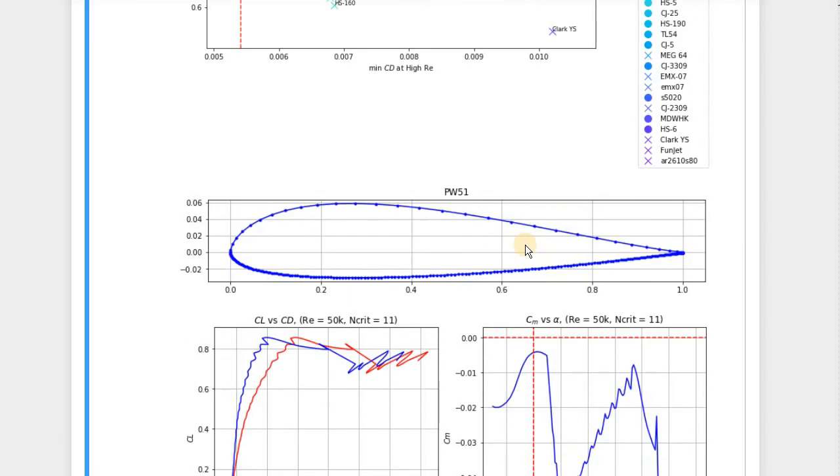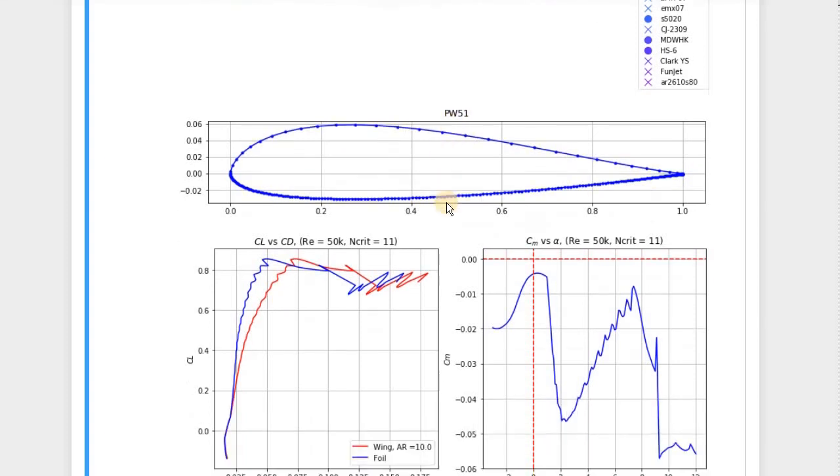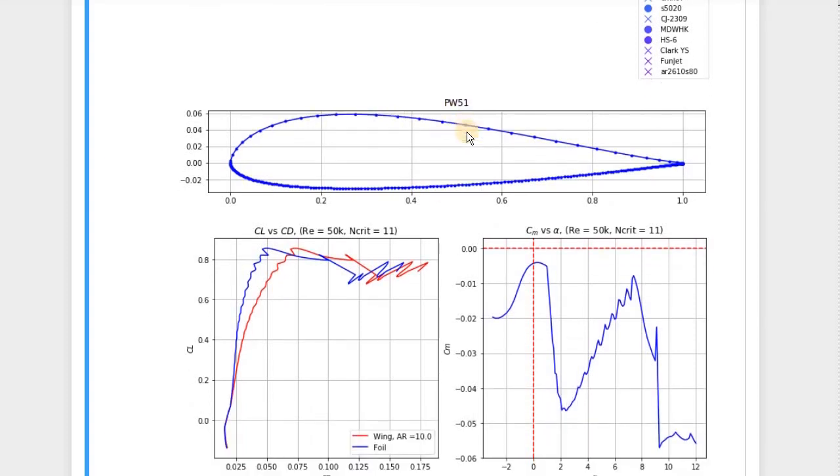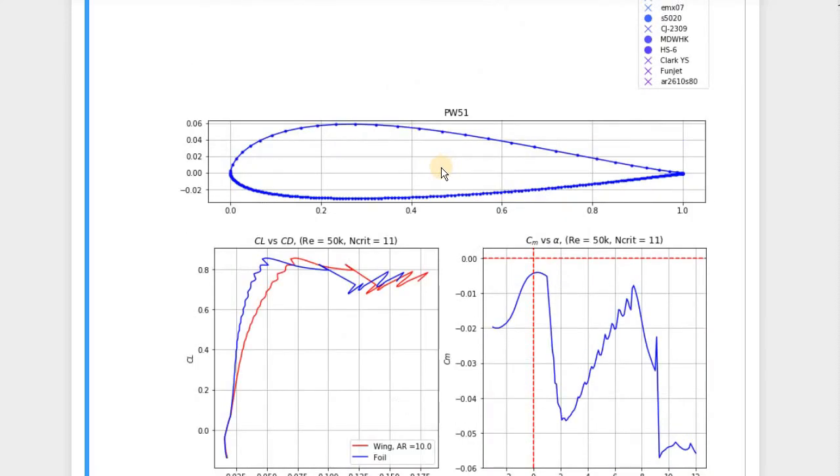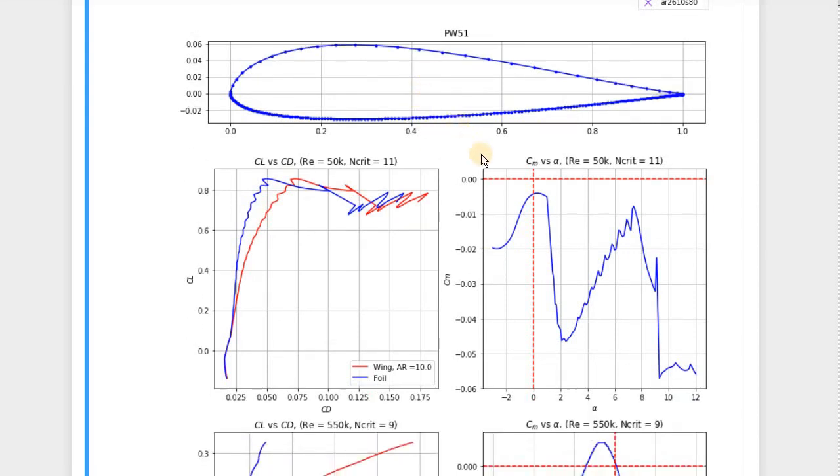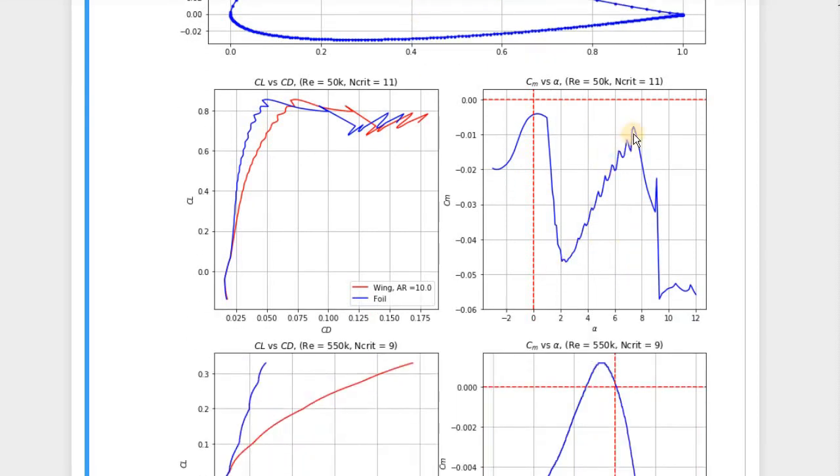So I don't think this airfoil is a good fit for slow flying airplanes. If you just use it for a flying wing, let's say just the usual plane, a flying wing, not some fancy design with delta wing and so on, if you have just a basically straight wing with a square kind of shape, then it's not going to be very stable because you have this growing moment with degrees of alpha.